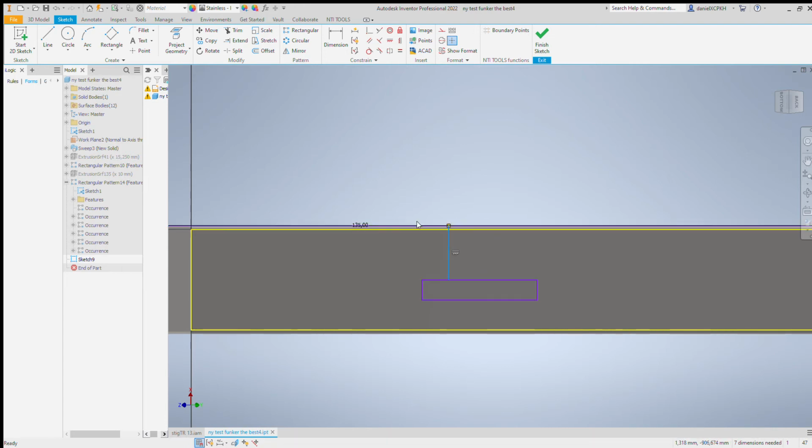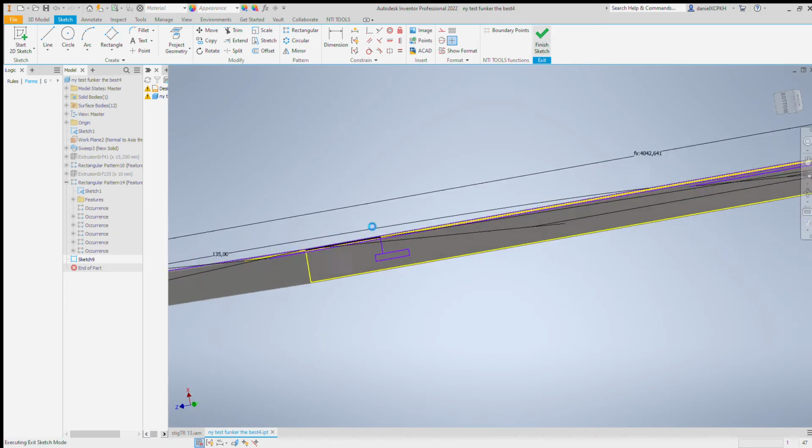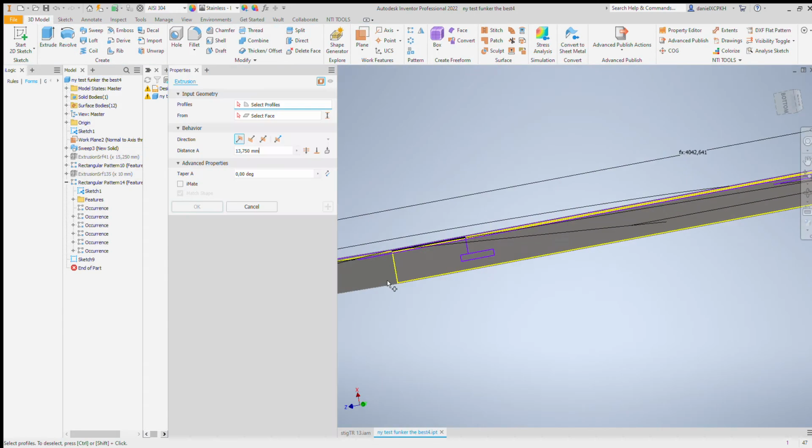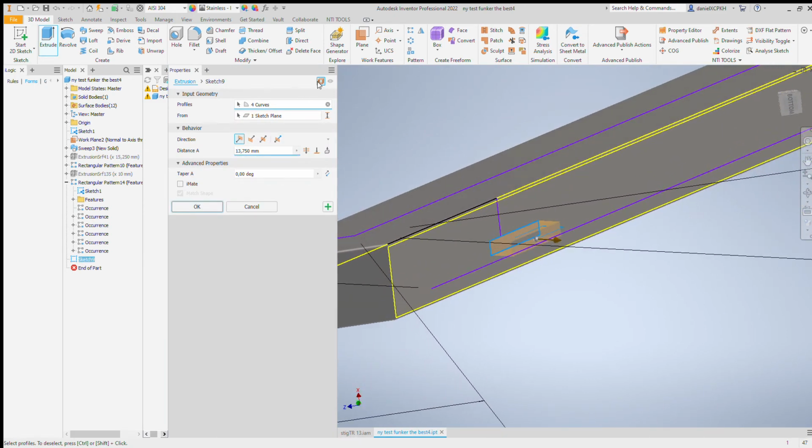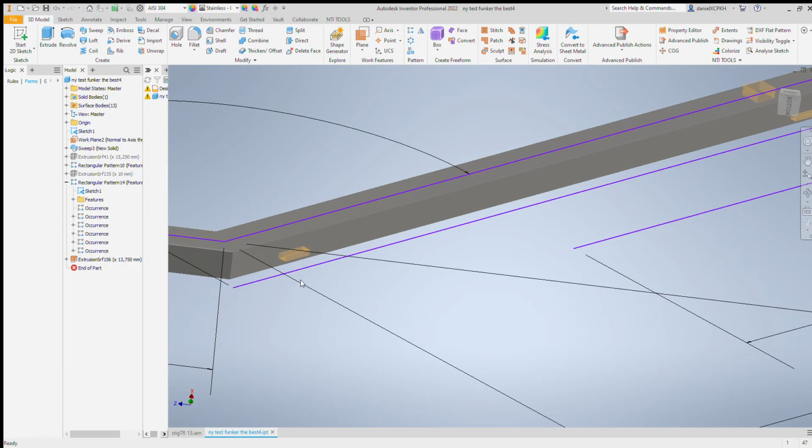Those two lines are very important here because they are going to act as constraints for this rectangle here. So keep those nicely done, one line here, one line there, and use 3 point, and bam bam. Now it's fully constrained and very nice. Go to extrude, just like that, and don't use the surface mode. Okay, that's it. Now I have this.